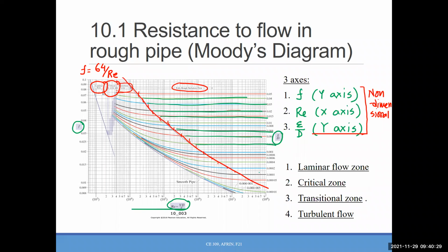So, okay, let me help you. For this Reynolds number, the same value, this Reynolds number, same value. That simply tells you that Reynolds number is not doing anything there, right? That means when the flow is very fast and very turbulent, viscosity is not playing a significant role. And that's why for any Reynolds number, you will have the same value.